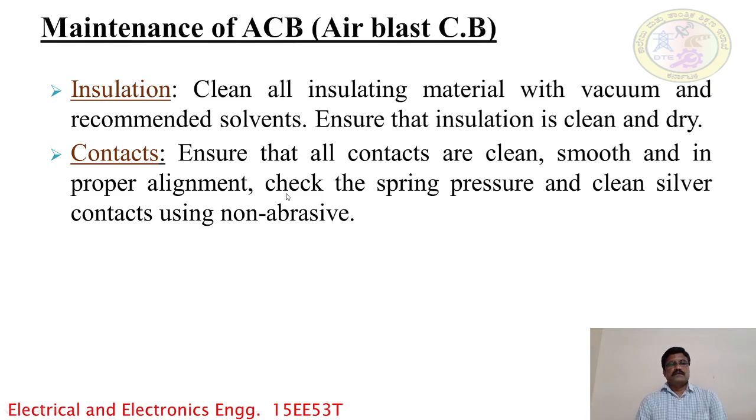Here also there are two contacts, similar to the oil circuit breaker: one is the fixed contact and the other is the movable contact. Ensure that all the contacts, either fixed or movable, are clean. The surface of the contact should be cleaned and smooth, and in proper alignment. The fixed as well as the movable contact should be aligned in a proper way.